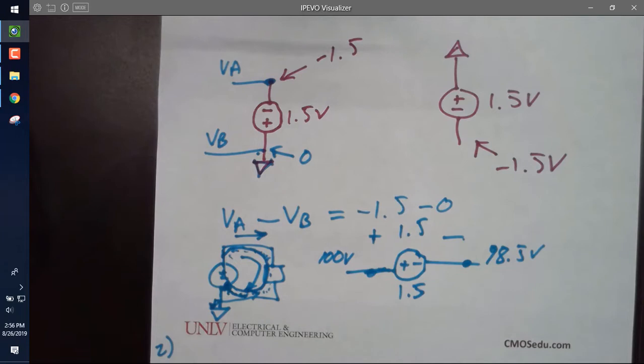And that circuit is to see if there's current flowing on ground, or it makes the hot and the neutral see if the currents are equal. Because if not, you could be the path of the current and get shocked. So you don't want current on ground. Current on ground's bad. So here, I draw the ground, but no current's flowing on it. So everybody got that? Okay.